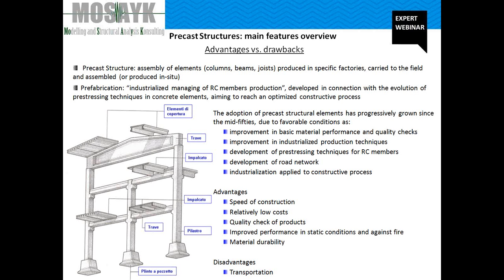Within this context, the main characteristics of our traditional reinforced concrete precast multi-story buildings, as well as one-story structures, are precast socket column-foundation connections, monolithic columns fixed at the base and with corbels at different heights in order to support the beam at each story, shear-resistant or partially flexural-resistant beam-column connections, which usually consist of steel elements without cast-in-place concrete, and horizontal structural elements simply supported or pinned to the column, with panels supported by the structure or by the foundation beam.